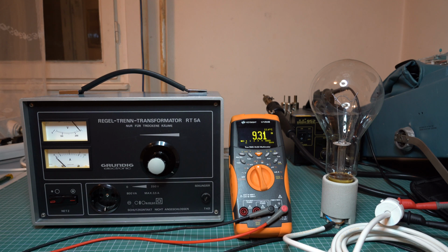And since the filament is working at a really high temperature, we cannot simply measure it at room temperature and assume that it will have the same resistance at an increased voltage. So taking all these into account, this means that the light bulb is not really a constant resistor. The light bulb is more like a dynamic resistor whose resistance depends on the voltage that powers the light bulb.